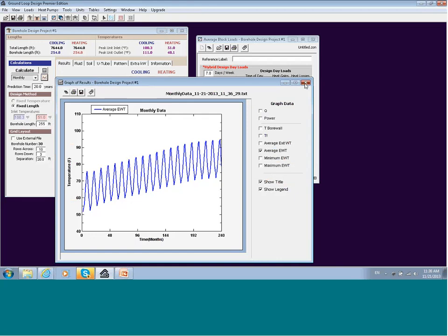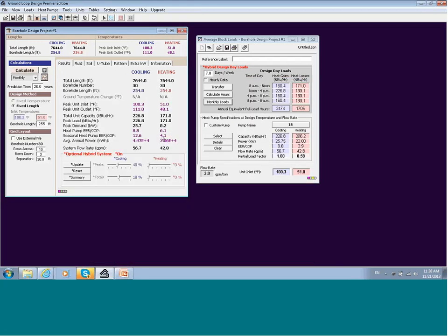So you as a designer can keep playing with these options until you get what you're comfortable with. Again, the big difference here on the monthly side is that now you have these two sliders you can control for cooling and for heating. Well, you only had one before. It just gives you a finer degree of control and potential accuracy. But in this example, let's just do one more to try to balance it out. What if I go to 50% here, then maybe on the total it goes up to 25%, something like that. I'll update the loads.